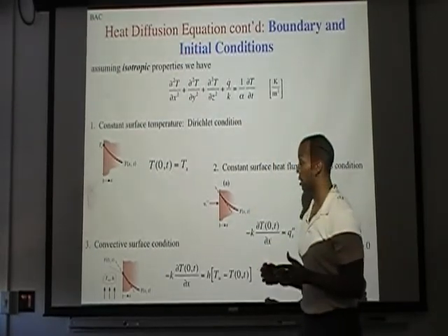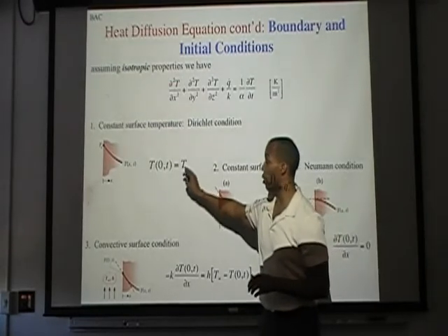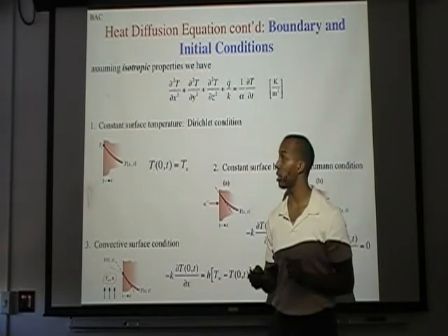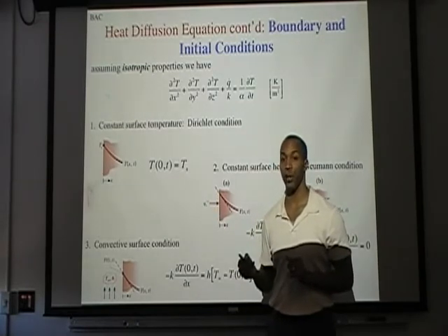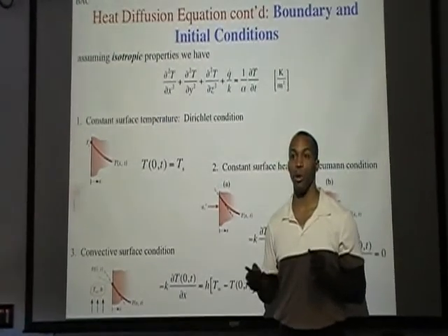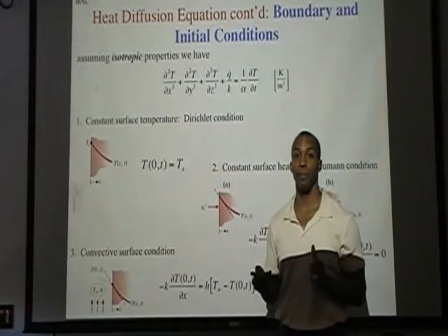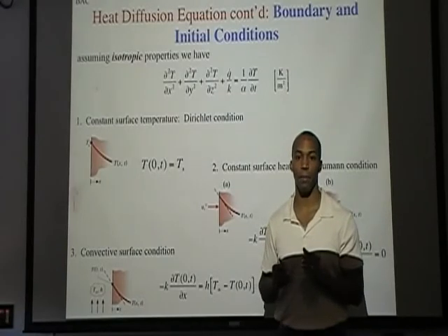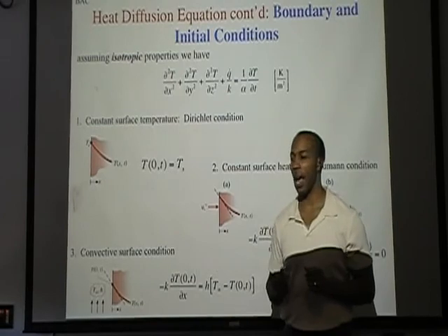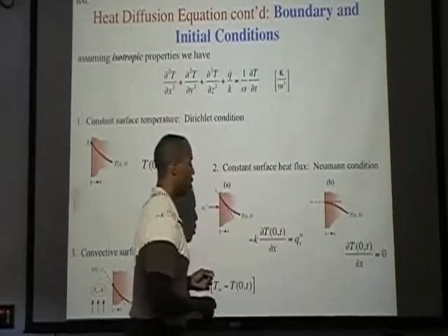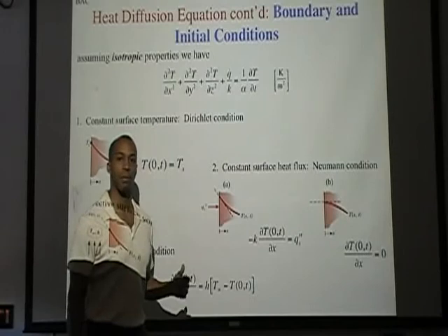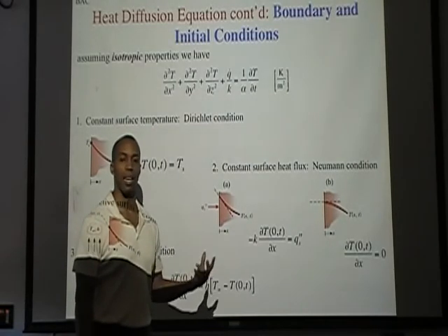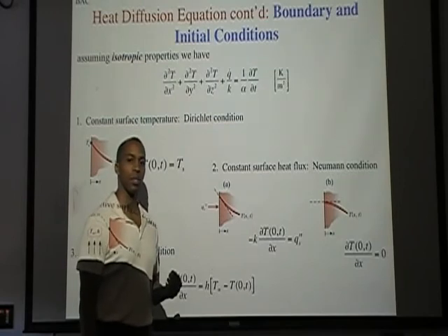So the point is that if, on one side of a wall where we have one-dimensional conduction, we fix a temperature, and we fix the temperature on the other side of the wall, we can solve the problem. We can solve for what the temperature distribution in that wall would be. But what if we had two heat flux boundary conditions, two boundary conditions of the second kind, satisfying that problem? I want you to think about that.